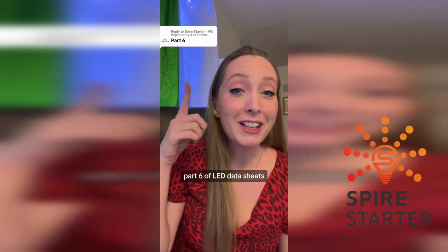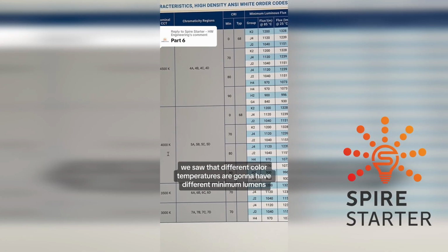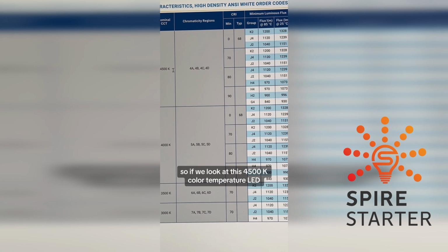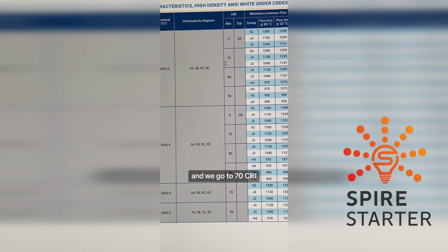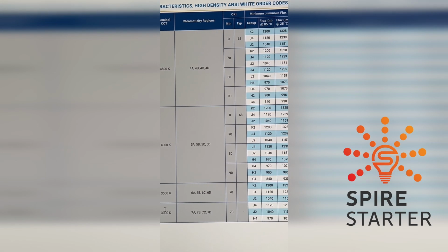Oh boy! Part 6 of LED datasheets, and we're picking up with binning, or LED bins. In the last part we saw that different color temperatures are going to have different minimum lumens, different minimum luminous flux coming out. So if we look at this 4,500K color temperature LED and we go to 70 CRI, then we'll see the lowest bin for the flux is this J2 group that's going to give us 1,040 lumens. But if we go to the same CRI for a lower color temperature, 3,000K, 70 CRI, then its lowest bin or lumen output is going to be 970 lumens.